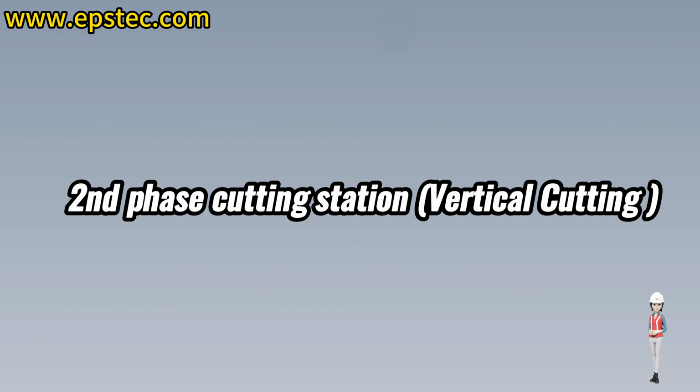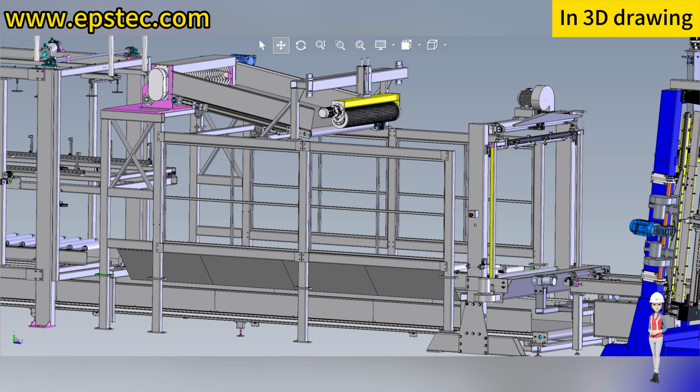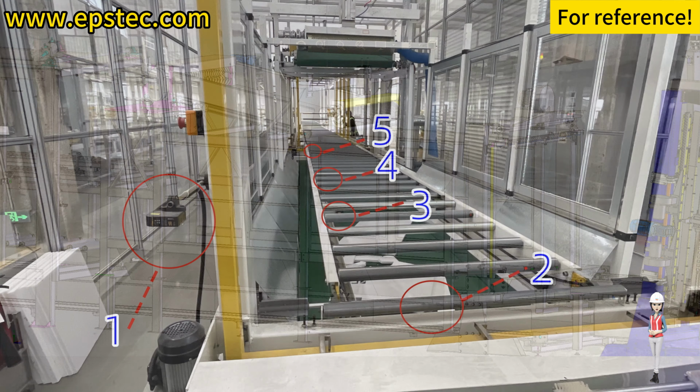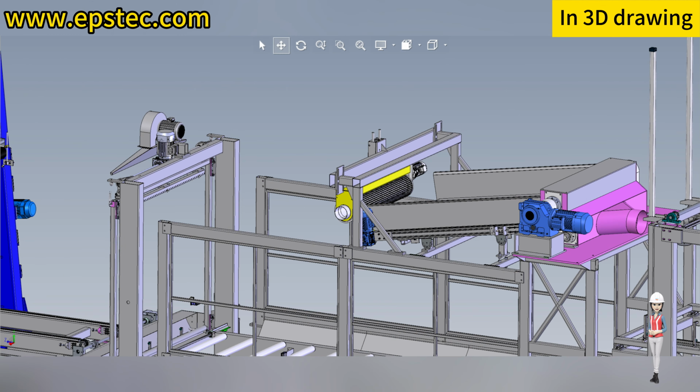Second phase cutting station. Vertical cutting. When the head of the EPS block enters the position of the first photoelectric sensor, the vertical cutting wheel starts heating, the cooling fan starts, and the vertical vibration cutting starts. When the head of the EPS block enters the position of the third photoelectric sensor, the vertical cutting lower conveyor starts. When the EPS block is transported to the position of the fourth photoelectric sensor, the top crusher system starts.